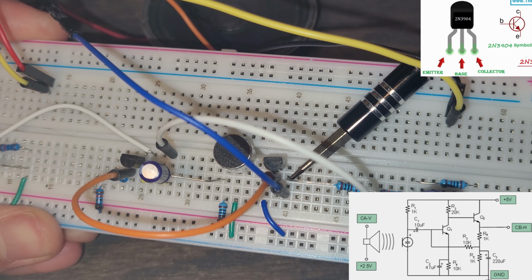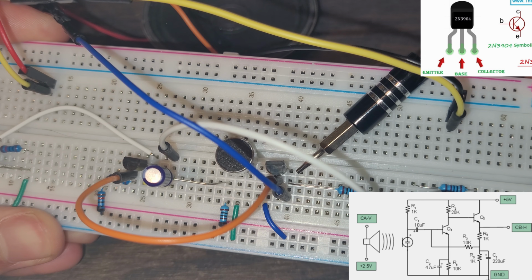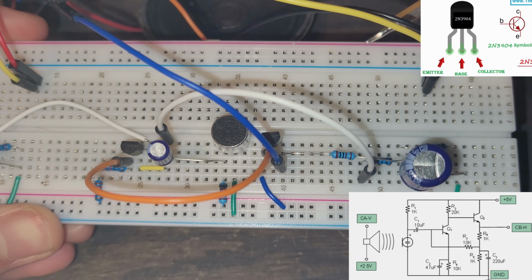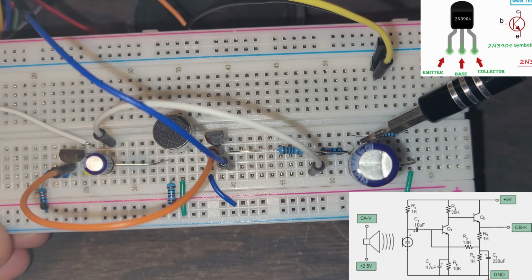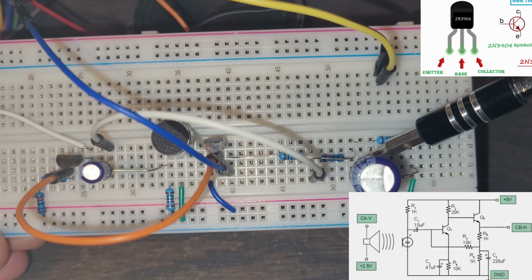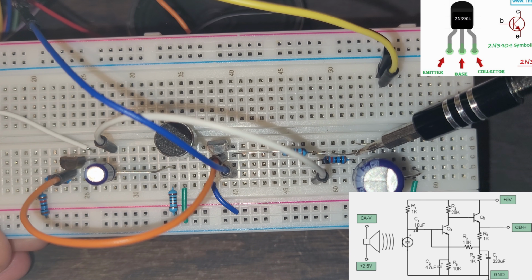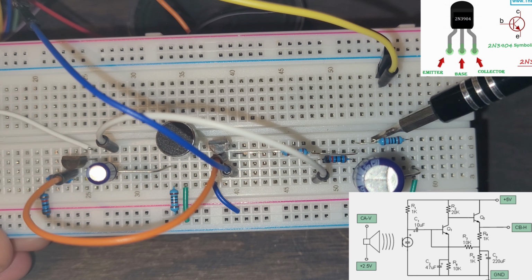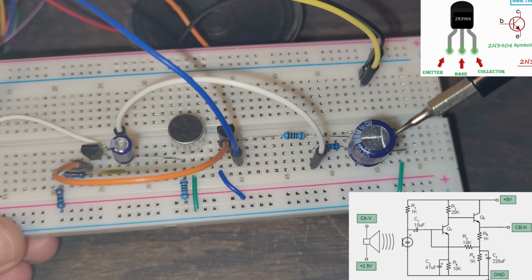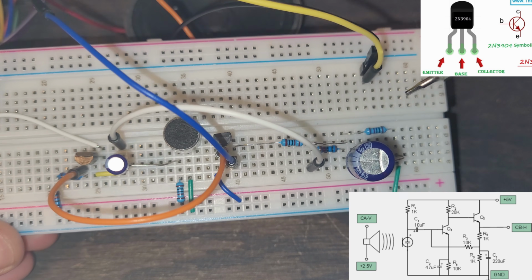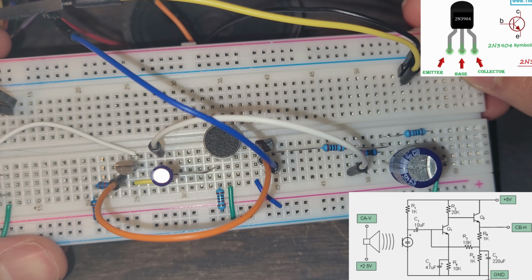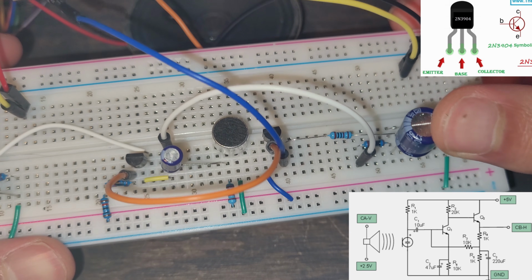We can see that the resistor and the emitter are in the same column. Then it's going to go from here, and it's going to terminate in the exact same place as our 10 kilo ohm resistor, which is right in this column right here. So the 10 kilo ohm terminates there, the 1 kilo ohm R4 terminates here. And then we have a 1 kilo ohm resistor across here that's in parallel with a 220 microfarad capacitor, and these are both going to ground. Again, this is on the very bottom right hand side. And that is going to be it.